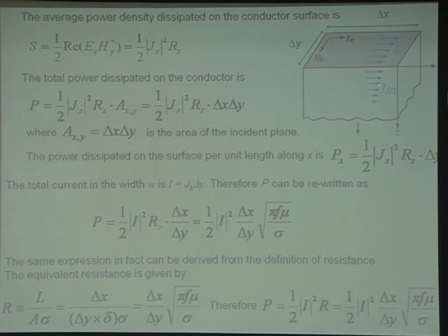The characteristic cross-sectional area is equal to delta y multiplied with the characteristic depth of the electromagnetic wave. So this calculation lumps the whole effect onto the surface, while this calculation imagines there is a specific thickness, the skin depth delta. So the two calculations are a little different, but the concept is the same. Realistically, the surface current does not exist. There must be some thickness.